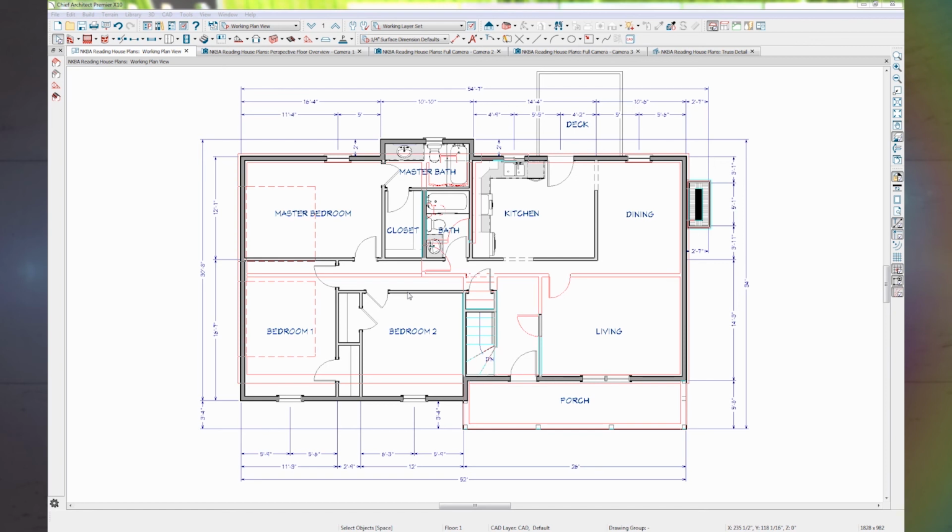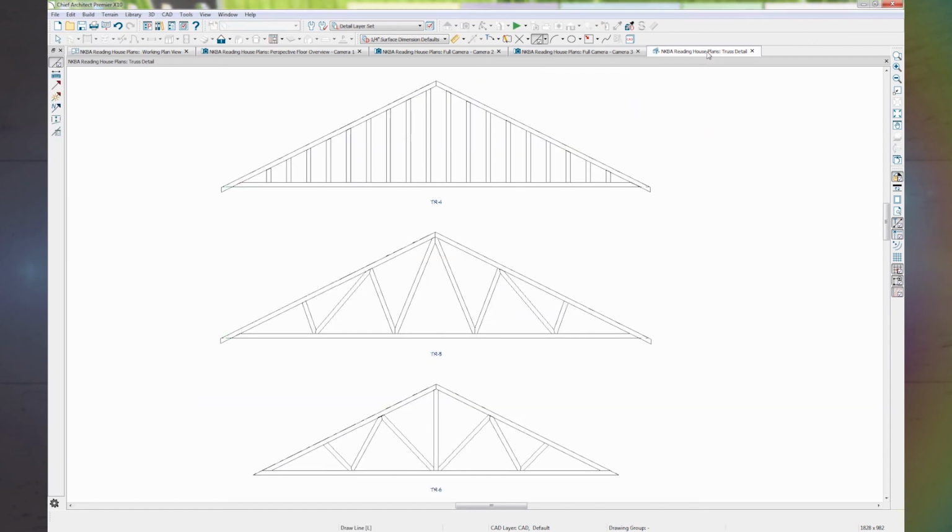The third bit of information is the spacing for the trusses, which will be 24 inches on center. Manufactured truss joists come in different shapes and sizes, like we see here. They're custom designed for each home and for the load that would be placed on the building. The weight of the trusses are transferred to the front and the back exterior walls.